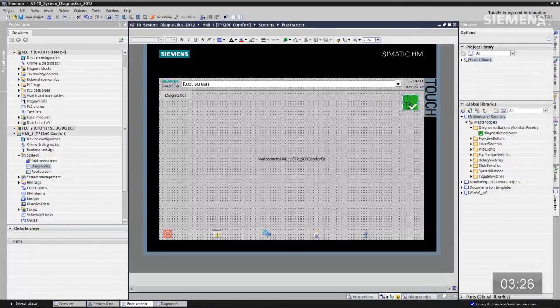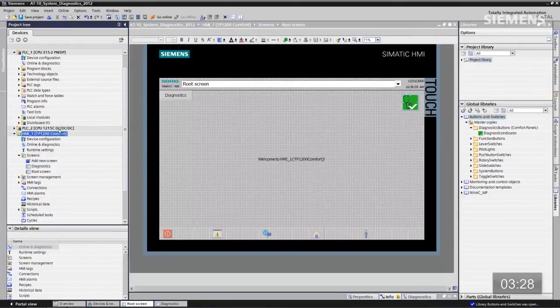Let go. Give focus to the main HMI. Click on Start Simulation. So now what we're able to do is virtualize this HMI panel. We don't have to buy the hardware. We can prove out whether or not this is going to work exactly for our application needs. And then at that point you can buy the hardware and test it in full. Ultimately we have a connection, I just saw it pop up, to the actual hardware architecture itself. So now our automation task is complete.